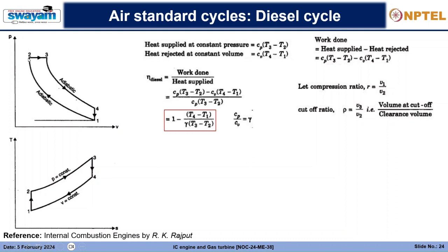And at point 2, the fuel injector releases a very calculated amount of fuel inside the cylinder at a very small space, in atomized form, and it will keep on supplying the fuel until point 3. So 2 to 3 is the fuel supplying time.